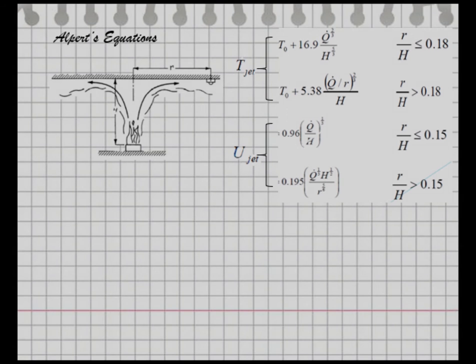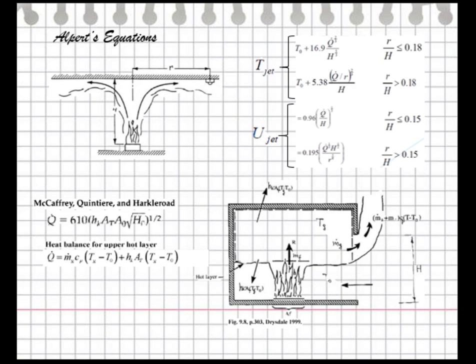Without the use of a powerful tool such as FDS, we would need to resort to hand calculations to obtain information that we need about the fire. Each time we carry out these calculations, we would obtain either the temperature or the velocity of the smoke at one particular position in the room. CFD does the same, but it does it hundreds and thousands of times. It also does it for all the areas in the room. This gives us a more accurate and dynamic picture of what is going on within the environment being considered.